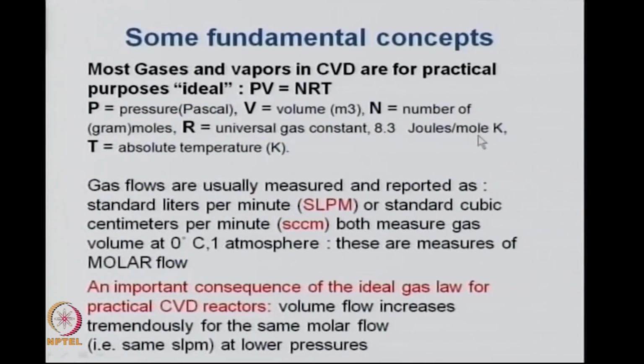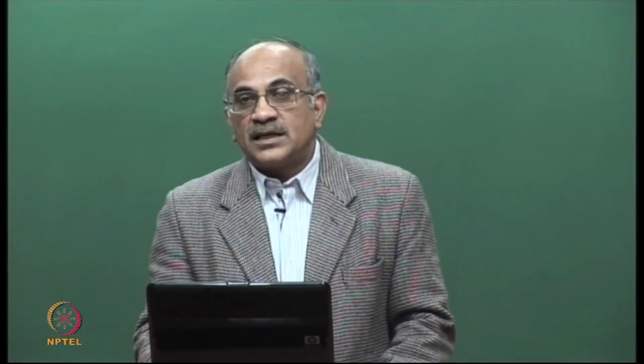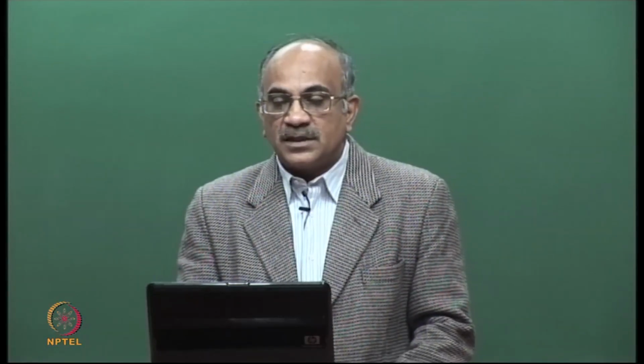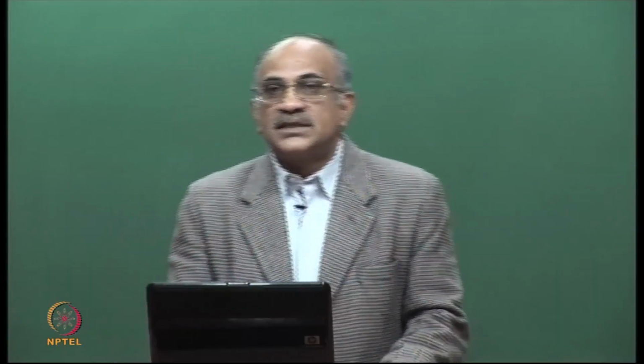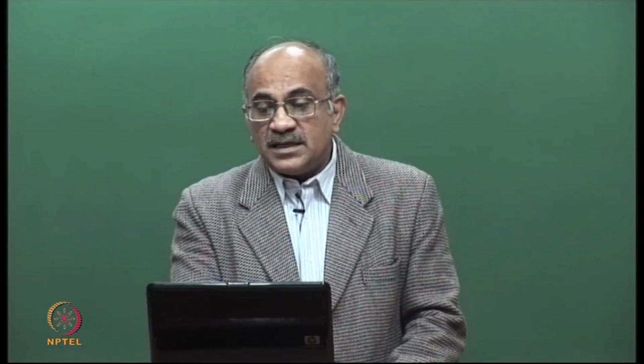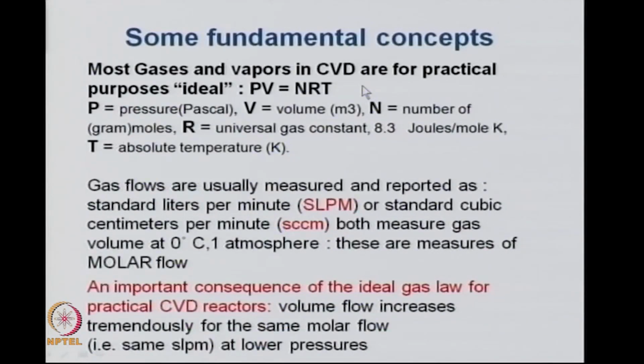Now, to understand the physics and chemistry of the chemical vapor deposition, we have to understand some of the basic principles of physical chemistry or gas laws, which are involved during this process of the gas molecules going on top of the substrate, and what kind of nucleation it is, whether homogeneous or heterogeneous nucleation, and how the growth of the film takes place, etc. So, the basic concepts in CVD start from approximating the gases and the vapors that you use to be ideal, and so they obey the ideal gas law.